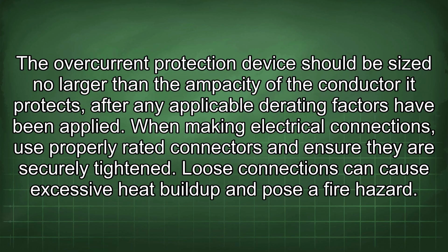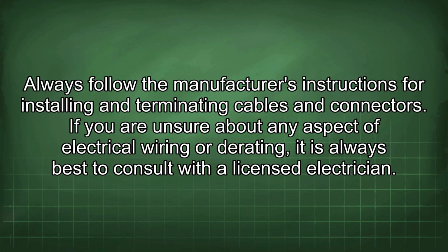When making electrical connections, use properly rated connectors and ensure they are securely tightened. Loose connections can cause excessive heat buildup and pose a fire hazard. Always follow the manufacturer's instructions for installing and terminating cables and connectors.